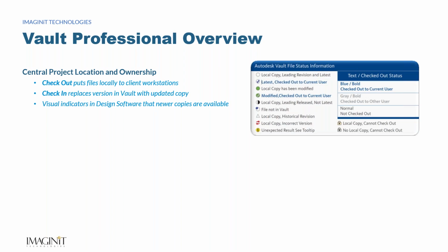It's a very common thing when you're accessing Inventor or AutoCAD files off a network that latency becomes problematic and overriding each other, and he who saves last wins scenarios prevail. With parametric software, it causes nothing but crashes because you're utilizing assemblies with parts and references which have such an interweaving of links that no two files should be accessing or saving it at the same time, and you end up getting crashes. So this is where Vault really prevails for system integrity for the users, as well as design integrity as they're working on something so they don't lose data.